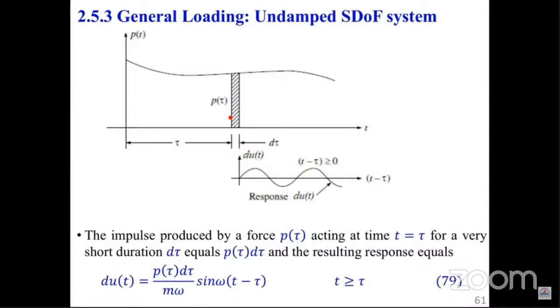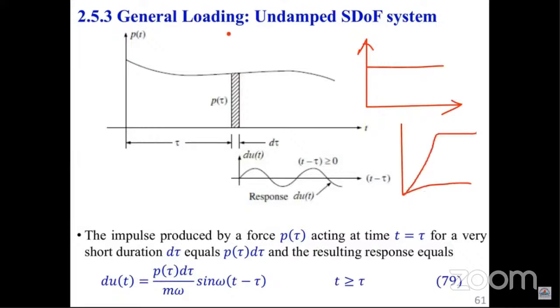Remember, we talked of cases when the forcing function is not harmonic, and we gave a number of cases. We said, for example, we could have the forcing function, the applied force, being constant, or we had a case whereby we could have a ramp, the force increases and then it remains constant. The worst case scenario is when we have a forcing function which cannot be described in any form.